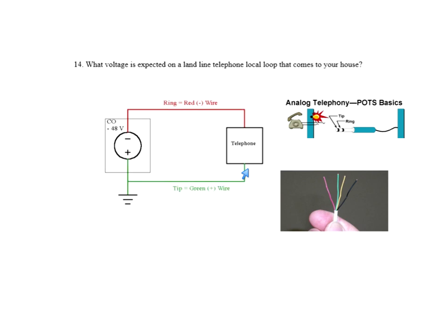But the CET question revolves around what voltage might you read at your home if you have your telephone on the hook and you were using a meter. Well, on your home, you might read up to about a negative 48. So negative 40 to negative 48 volts.